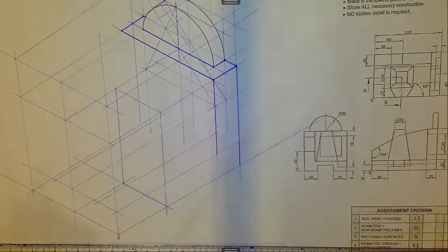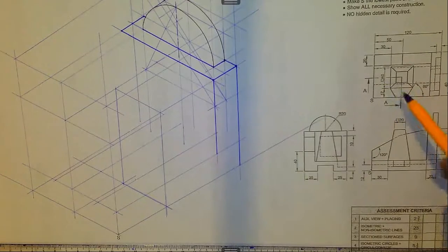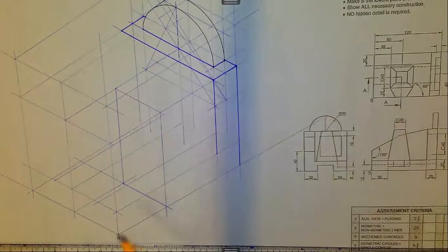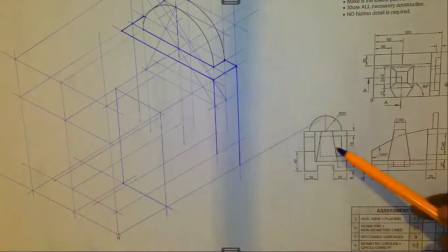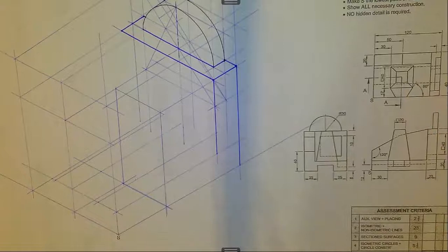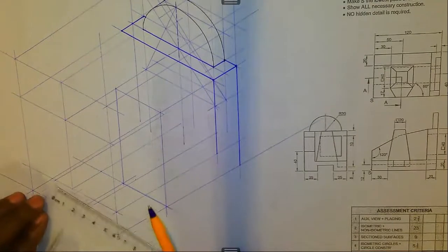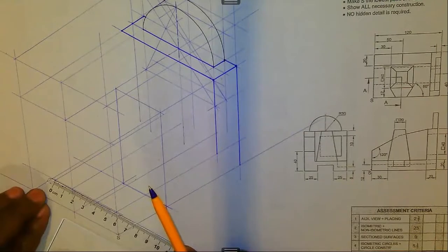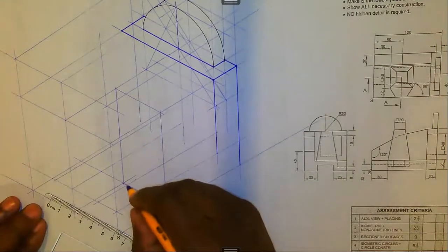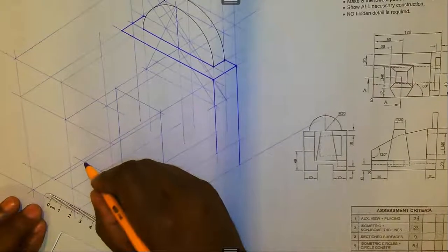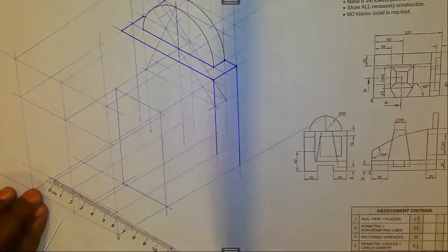So we need to shift our cutting plane slightly, because it is cutting through the center of the square, not necessarily the center of the given part. So it's cutting through the center of the square. Measured from here to there, that's 40. What it means, we have got our point here and another point there. Let's find the midpoint.